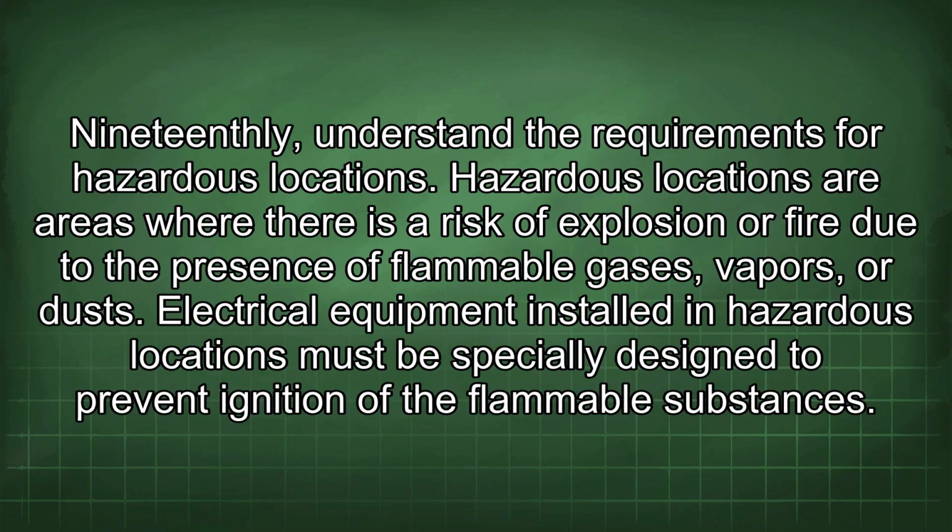19thly, understand the requirements for hazardous locations. Hazardous locations are areas where there is a risk of explosion or fire due to the presence of flammable gases, vapors, or dusts. Electrical equipment installed in hazardous locations must be specially designed to prevent ignition of the flammable substances.